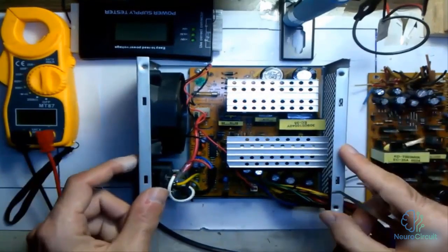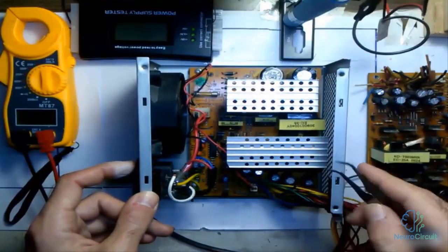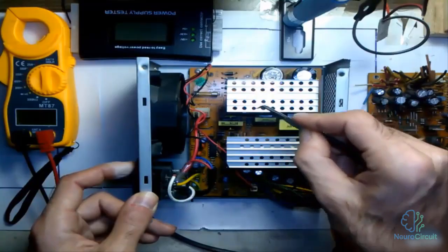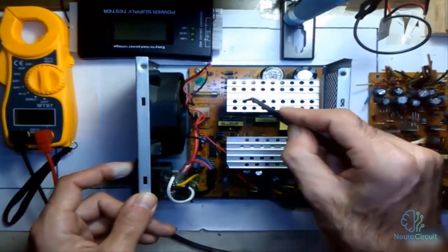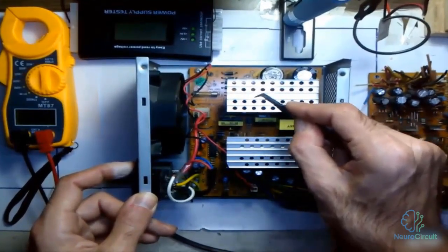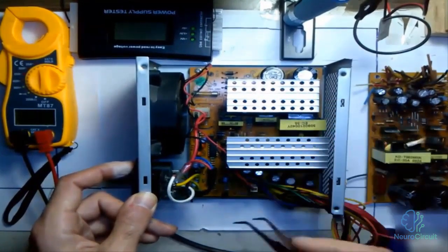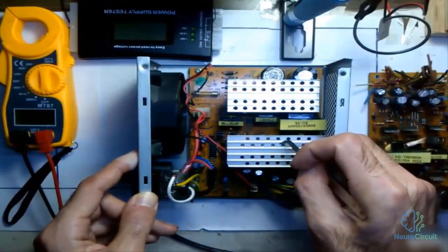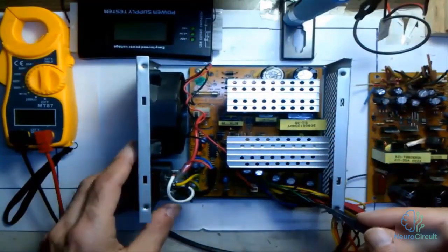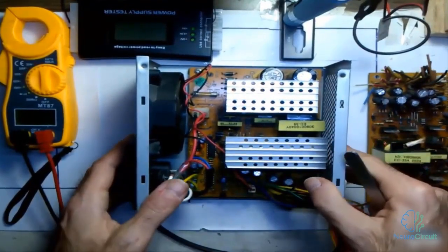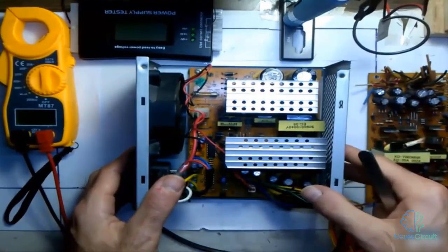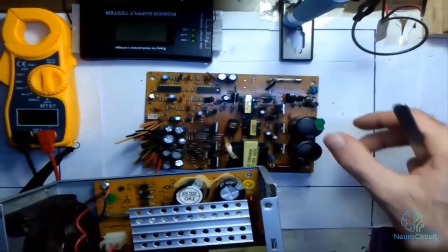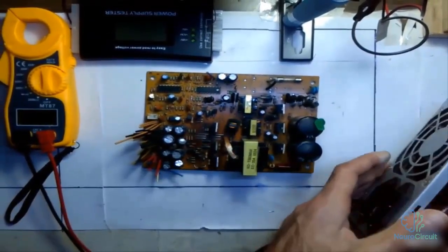Here, we see a switching power supply specifically for computers, which has two heat sinks, the first heat sink and the second heat sink. The first heat sink, usually the transistors are attached to it, and it dissipates the heat from the primary circuit's transistors. The second heat sink you see here is usually related to the Schottky diodes that are present in this power supply. So that I can give a better explanation, I had previously prepared a power supply here and removed the heat sink so we could access its components more easily.